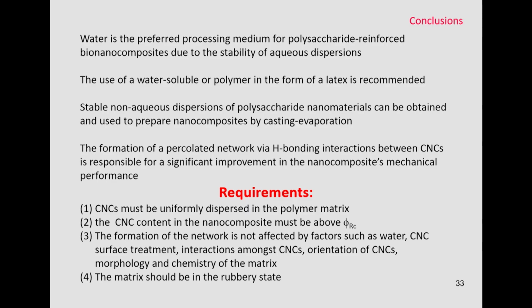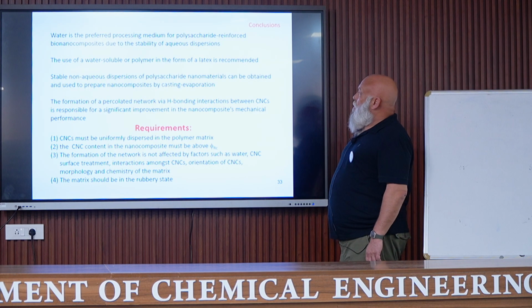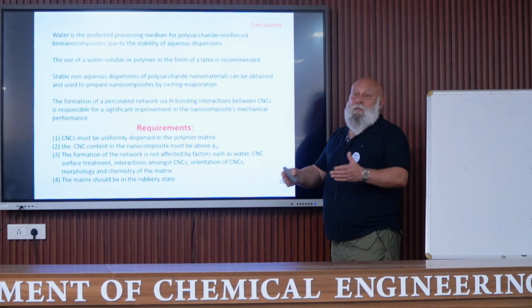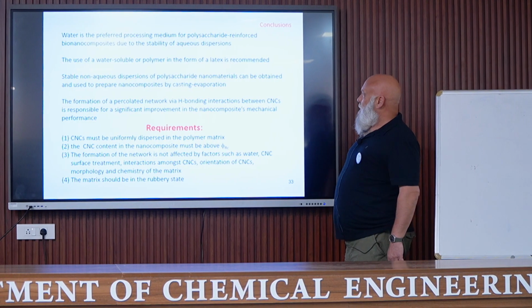Water is the preferred processing medium for polysaccharide reinforced bio-nanocomposites, and this is due to the stability of aqueous dispersions of nanofibrils and nanocrystals. The use of a water-soluble polymer in the form of a latex is recommended, but of course it limits the number of polymer matrices.